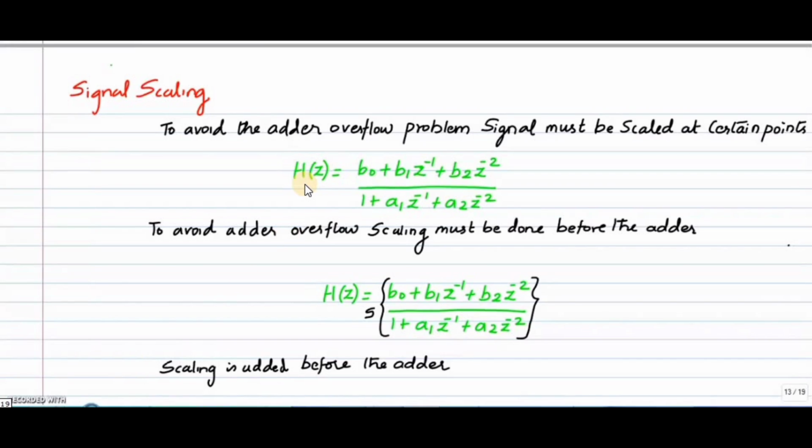So in this video, we are going to discuss scaling. The digital filter must be properly scaled in order to prevent overflow in fixed point implementations. Overflow is clearly a serious problem since the errors introduced are very large. Therefore, in order to prevent the overflow, we scale the input to the filter such that overflow cannot or is unlikely to occur.